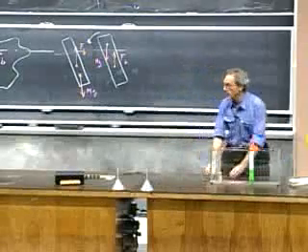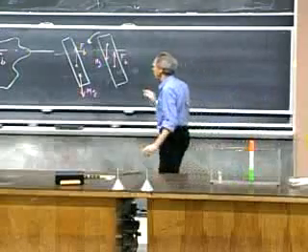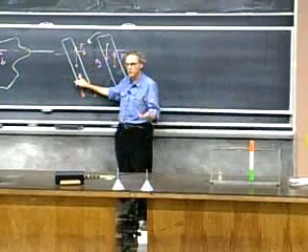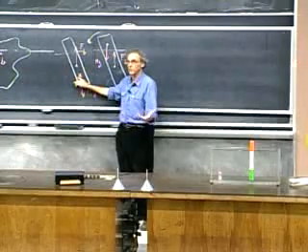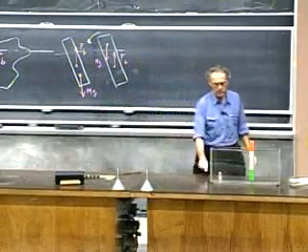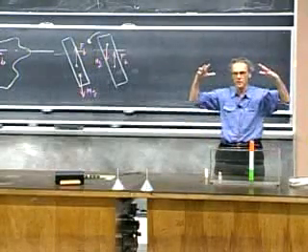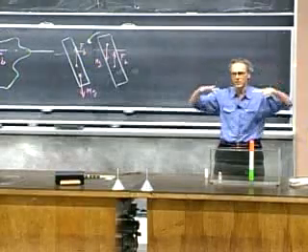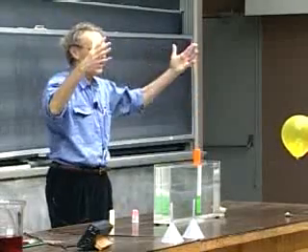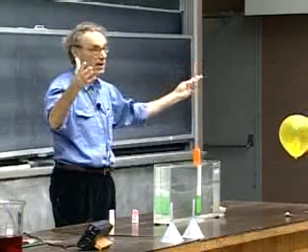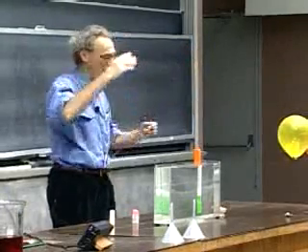And that's very important, therefore, with ships, that you always build the ship such that the center of mass of the ship is as low as you can get it. That gives you the most stable configuration. If you bring the center of mass of ships very high, in the 17th century, they had these very massive cannons, which were very high on the deck, then the ship can capsize. And it has happened many times, because the center of mass was just too high.